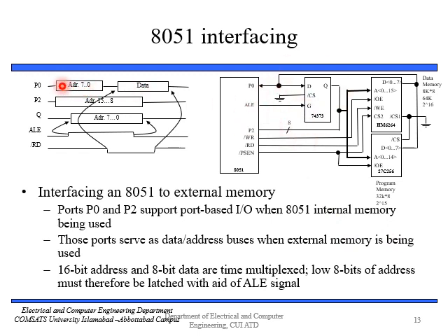Here you can see in port 0 we have the address from 0 to 7, and then we have data, that is our 8-bit data. So 8-bit address, 8-bit data, and in port 2 you can see we have the address from 8 to 15. So what we are going to do is latch this address, so this address will be on the address bus.